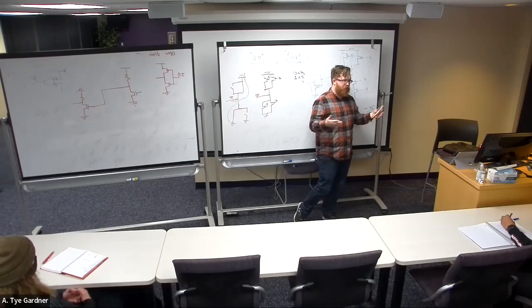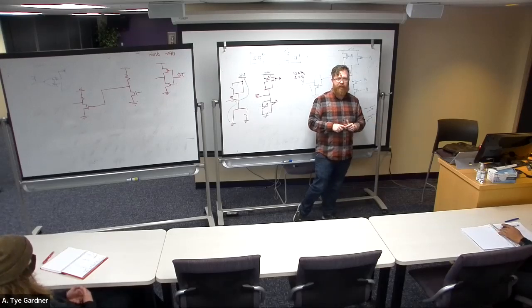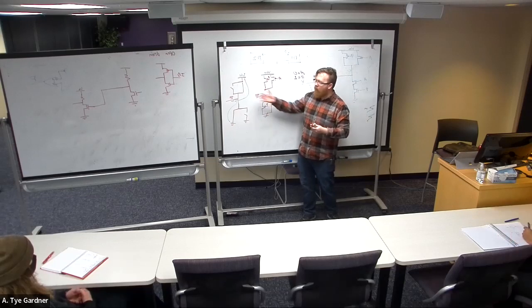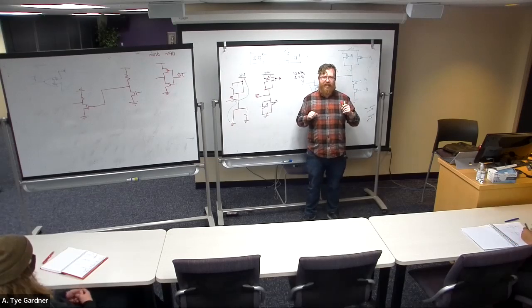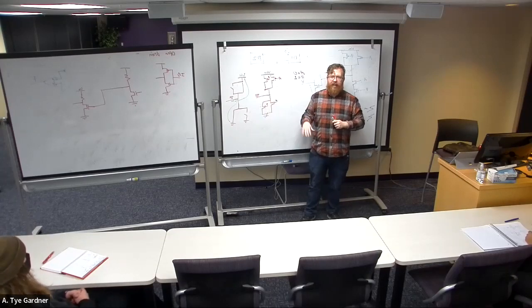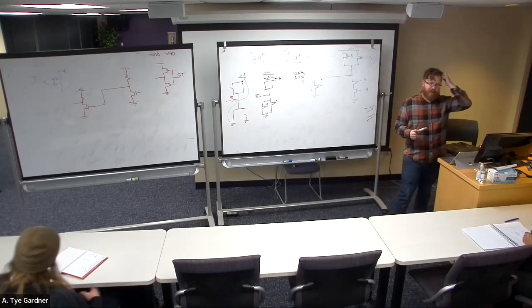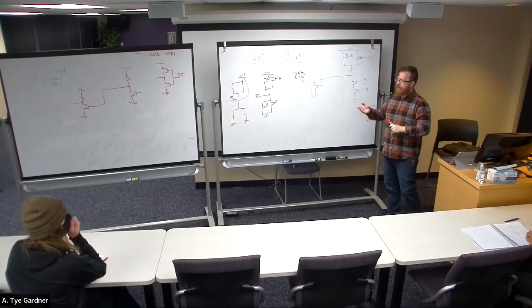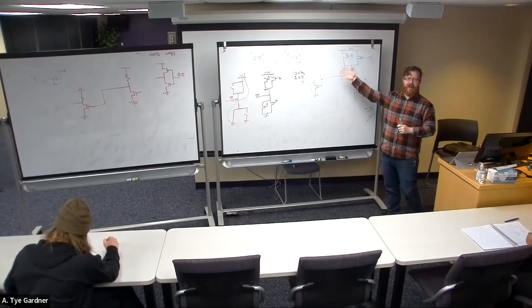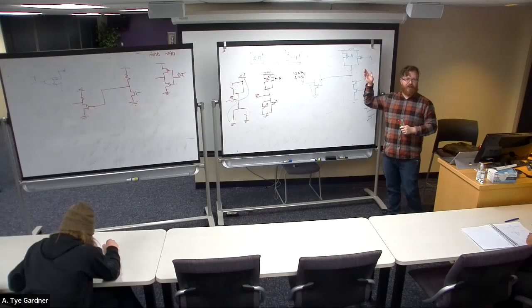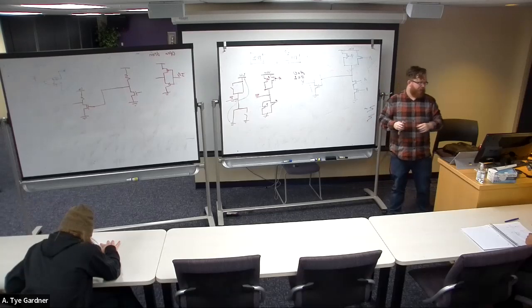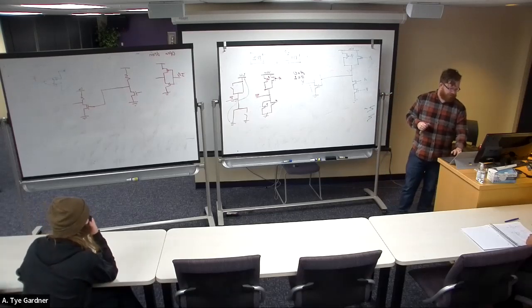And so it breaks. That's why I need to have one of the pull up or pull down in series, because you don't want a situation where some combination of inputs does this. And in this situation, it's really easy to recognize, right? On an exam, I could ask you to analyze a circuit. As I said, I could draw a real life XOR gate up here, and you wouldn't know what it is because I haven't shown you, but you could puzzle it out, get the truth table, and you'd be fine. That's all you have to do with that.